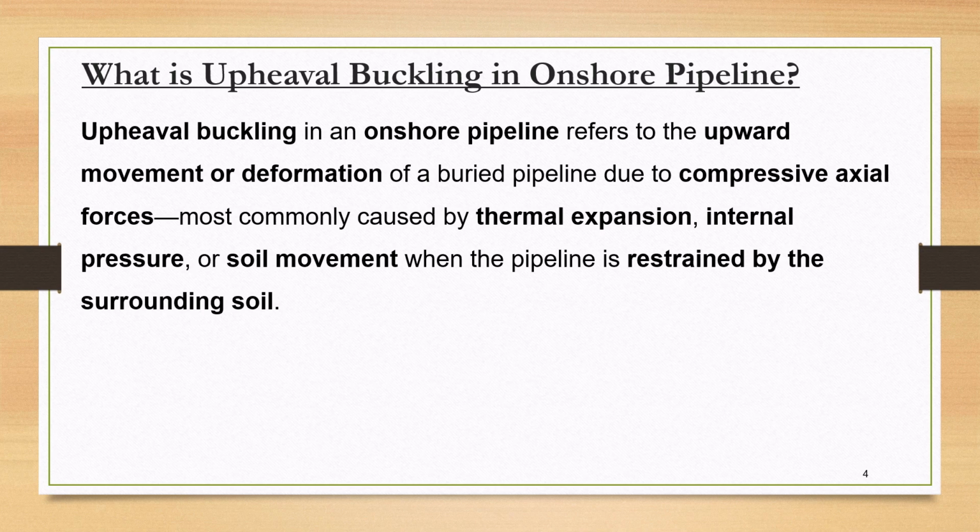It is a well-known fact that if a pipeline is buried, we can assume that both ends of that pipeline are fixed, acting as anchors. When the temperature changes from the installed temperature to the design or operating temperature, due to that temperature difference there will be a generation of thermal force, which in turn will result in thermal stress in the pipeline system.